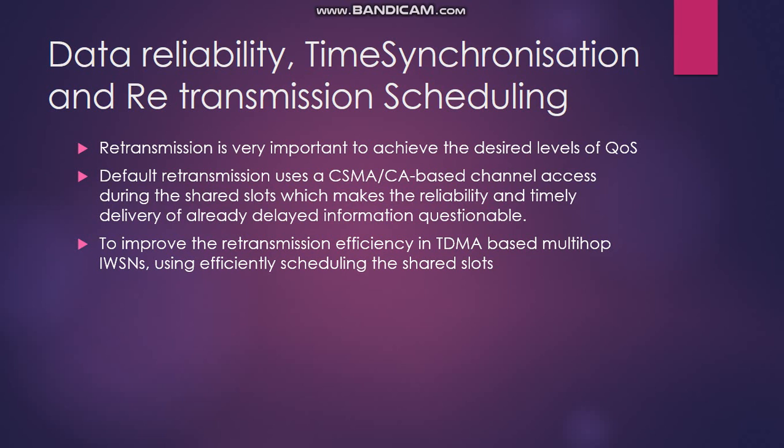Also, for certain communication types in IWSN, retransmission is scheduled. The shared slot is provided in the 802.15.4 standard for this purpose, but the default retransmission uses CSMA/CA based channel access during the shared slot, which makes the reliability and the timely delivery of the already delayed information questionable.